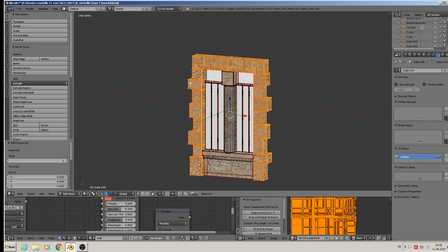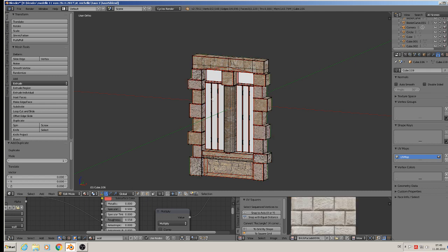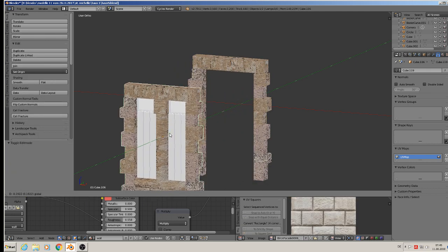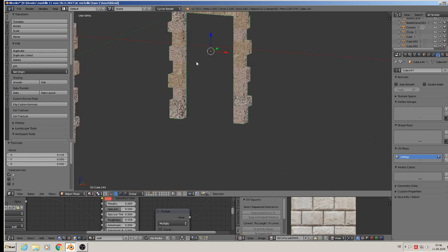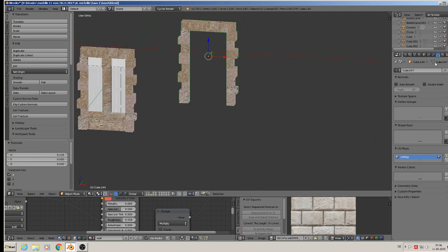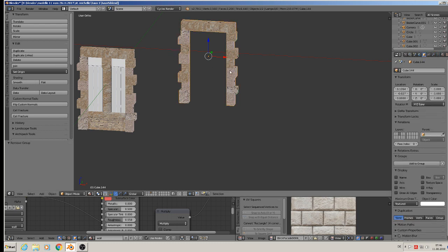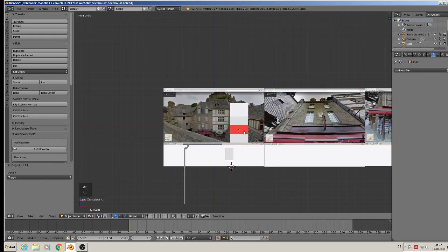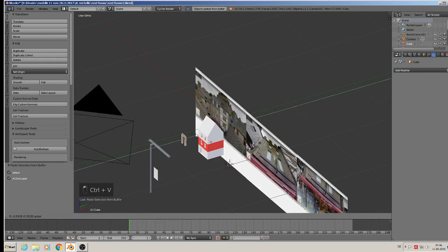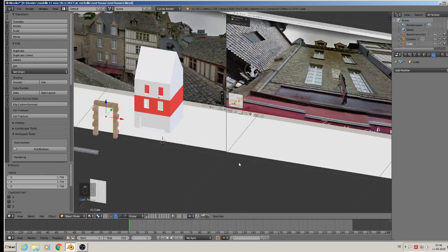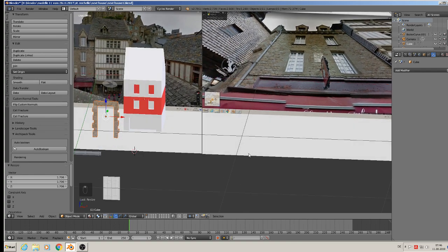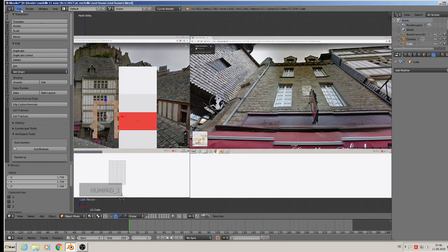So Shift D, P to separate selection, then move it away so we have that left, and that is okay. So here in object data, we delete the group, so the green one is gone. Control C to copy and bring it in the other project, and Control V, paste it there. So that nearly was it, but we must try. File, save.